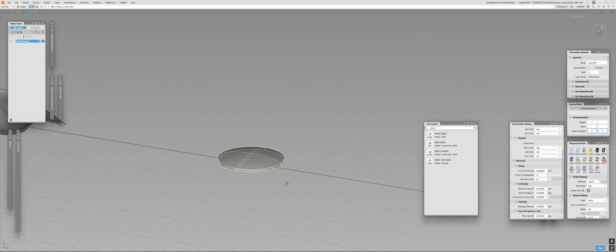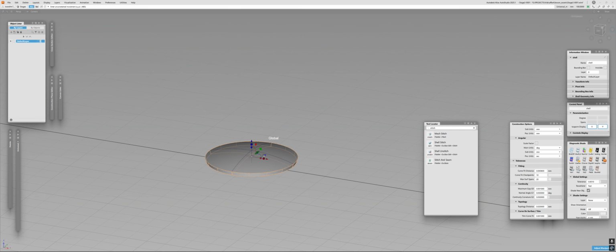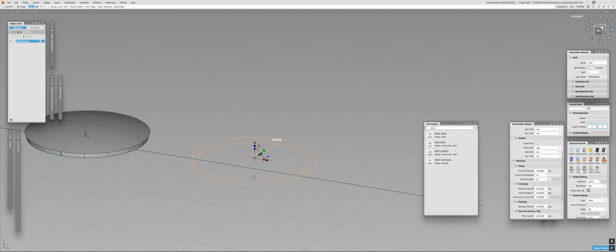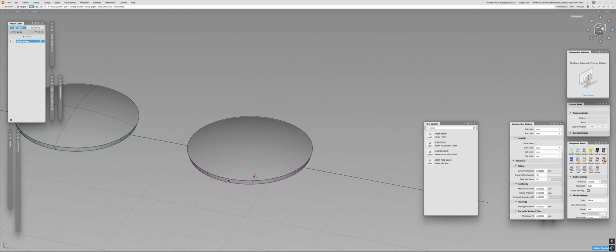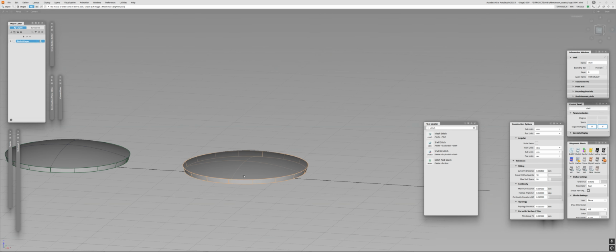Now you go to the shell, Stitch. Let me activate that, and stitch this one. And this becomes a stitched version of the model. Now in Alias, it's called a stitched version of the model. In all other CAD systems, it's called a BREP, or boundary representation, or even better said, a closed BREP, which means closed boundary representation. Closed means it is watertight within the desired tolerances.